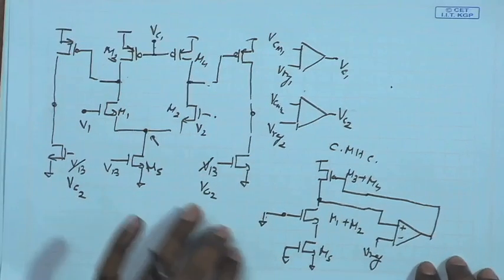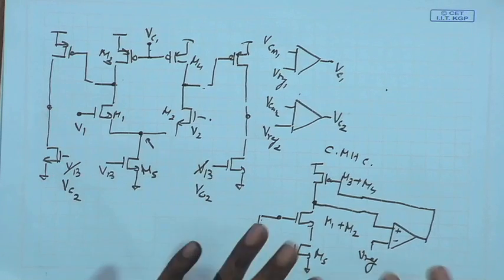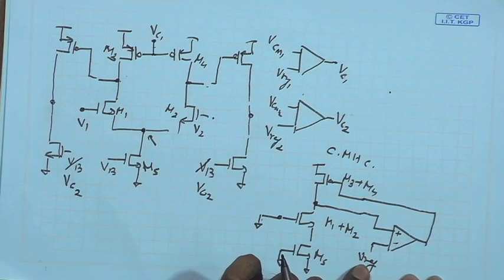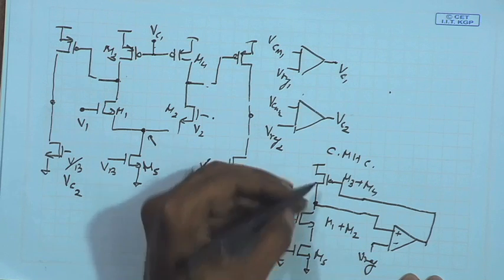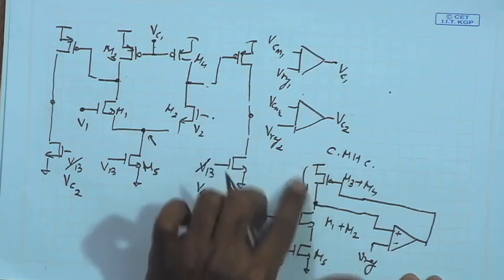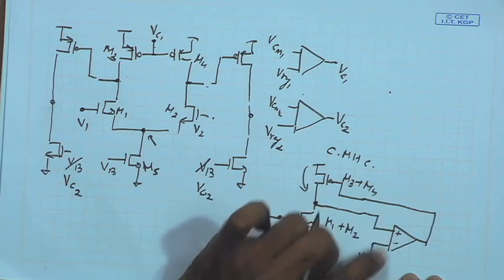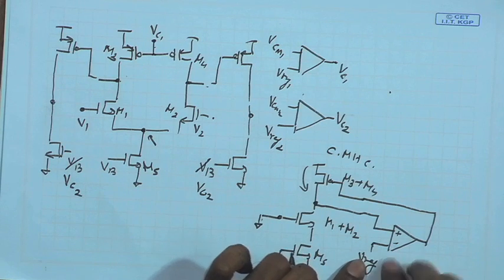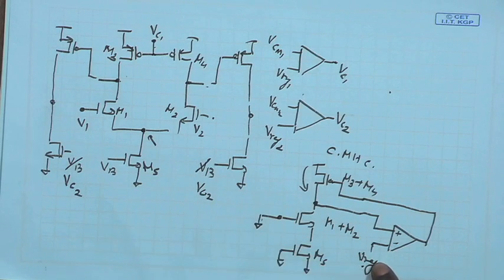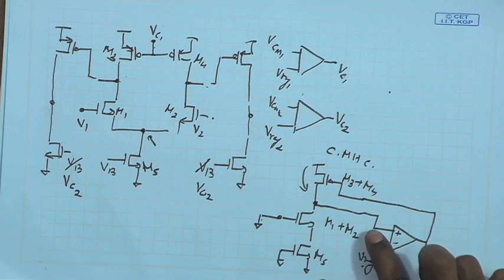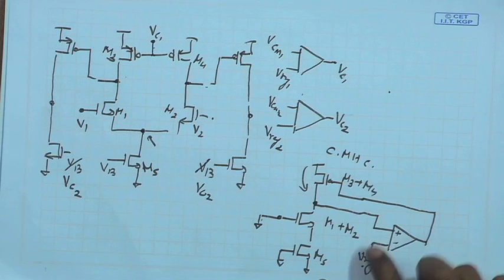Now, in this case, we can assume the Vref to be my input port, and I can see that the final voltage that is fed back to the other terminal is at the opposite polarity. So, if I assume that the Vref is an input signal which I am willing to change to set up a new common mode voltage, we can see that the feedback voltage that is coming over here is at the opposite terminal.